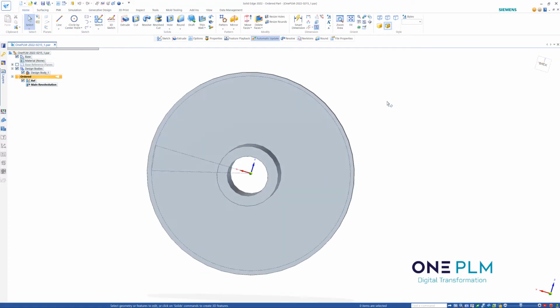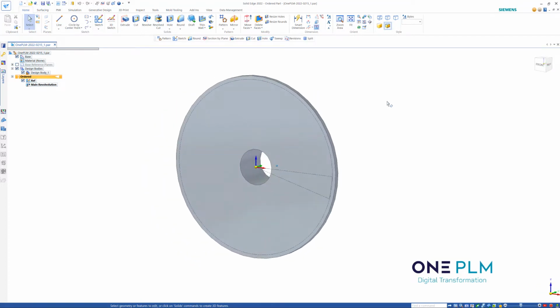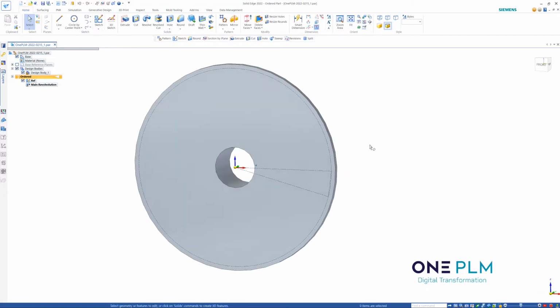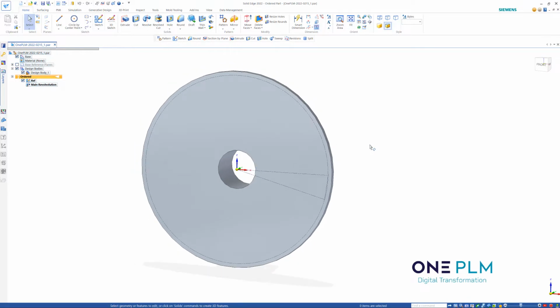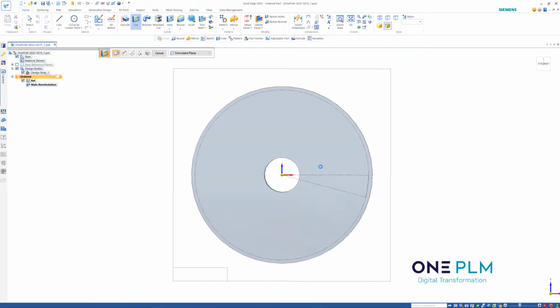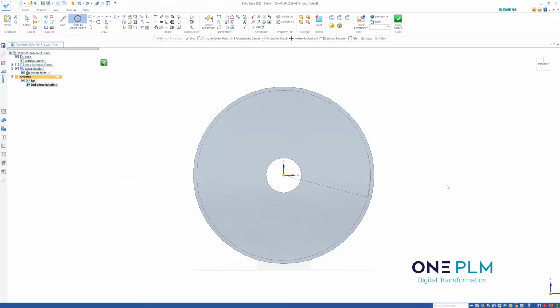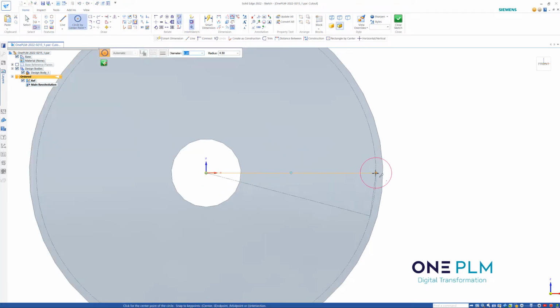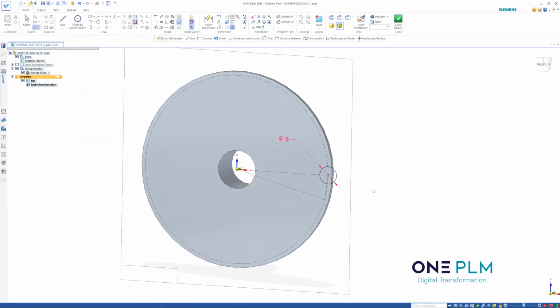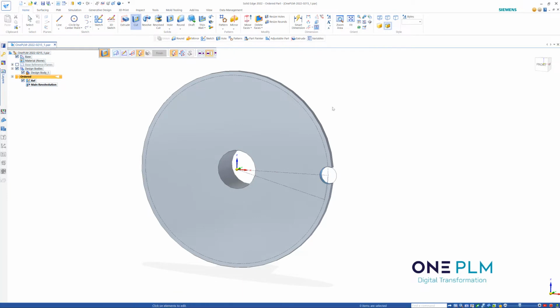So the next thing we're going to have a look at, so we've got a few different ways we can do the gears on here. So the most simple way is to do a cutout, just do a basic circular cutout. So our rollers are going to be 9mm on here, so I'm going to do a circular cutout 9mm, and I'm going to go and just place that on the end of that line. I'm going to cut through on there.